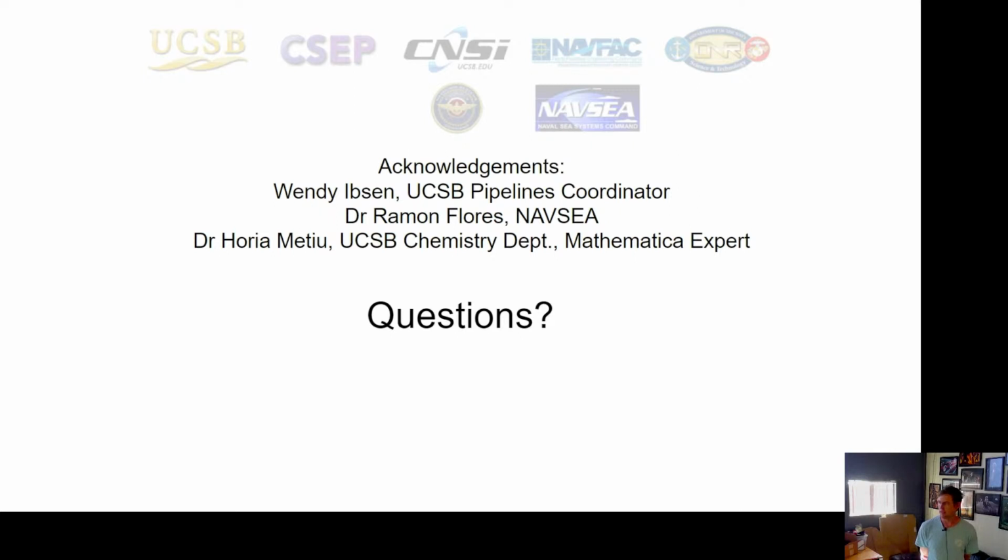So yeah, that just becomes a data handling and hardware issue. You need a channel for each individual electrode, and they all need coax cables. So it gets very cumbersome very quickly if you want to have a whole bunch of electrodes in an array. You can do it, and your noise also goes up pretty quickly with how small your electrode is. So there's kind of a lower bound on the size as well. You don't want super small electrodes because then you're just getting mostly noise in all your measurements. So yeah, trade-off.